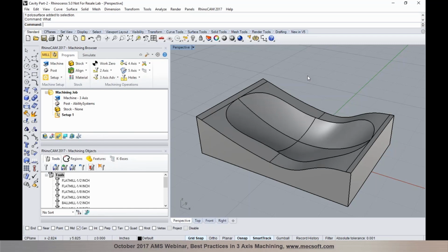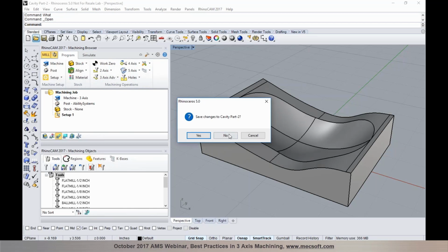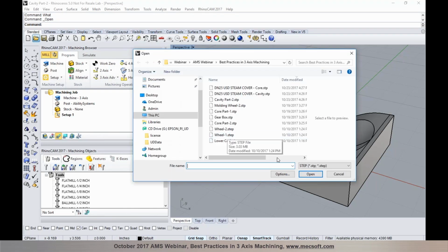That's also a benefit in addition to being able to program tool paths in 2.5, 3, 4 axis or 5 axis. Working with solid models, you can also take advantage of the feature detection and machining as well. Now, let's take a look at some of the downsides of working with just surface-based models, where you may have some gaps or issues with surfaces.